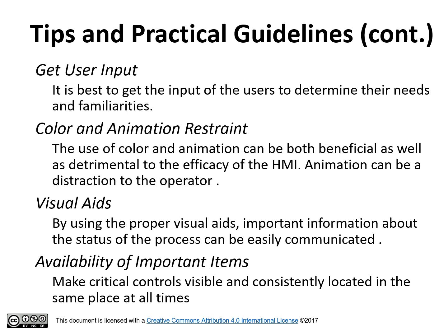Availability of important items. Make critical controls visible and consistently located in the same place at all times. For safety and security reasons, operators must have immediate access to shutdown, stop, alarm, and other emergency controls at all times.